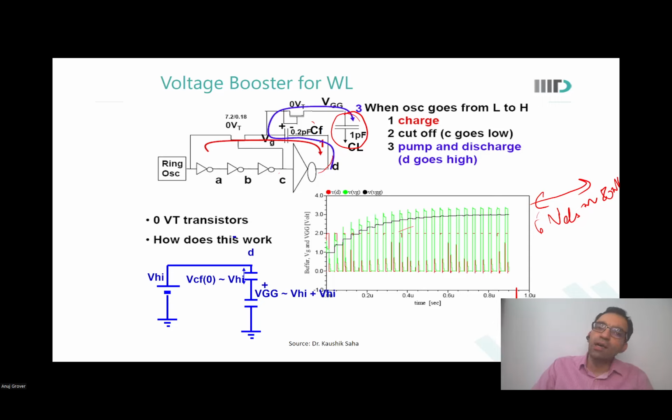Yeah. So junk has come. You will either bring OEN after the output is stable, which could be called late read, or if OEN was already low, then there would be some junk on the output, but you will latch the output only later. OEN is only the output being driven to the output bus. The output bus would also latch it somewhere. That latching should happen after the total access time has elapsed. Is that okay? Yes, sir.